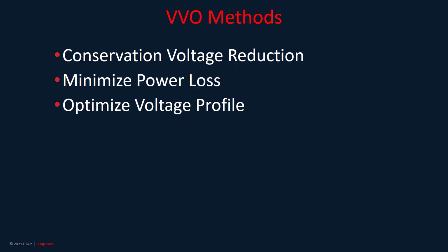Volt-var optimization includes conservation voltage reduction, or CVR, functions that are used to calculate and maintain acceptable voltage, for example, 120 volts plus or minus 5%, at the service entrance of all customers served by the feeder under all possible operating conditions. CVR is used to flatten voltage profiles and lower overall system voltage while staying within the specified ANSI or IEC voltage limits.